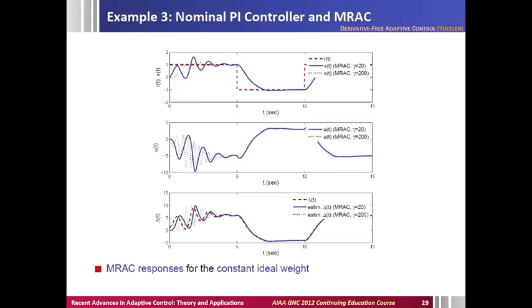And also, in addition to that, if we use a nominal PI controller with the integration-based model reference adaptive control, then we can have too much integral effect. And from the classical robustness standpoint, if you have more integral effect, basically your margins get lower and lower. So here is the case. This is the model reference adaptive control. Baseline is PI.